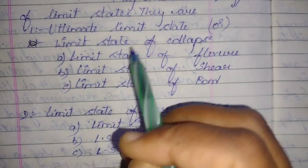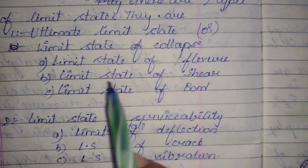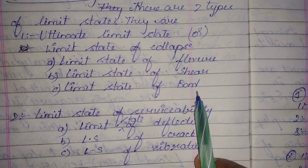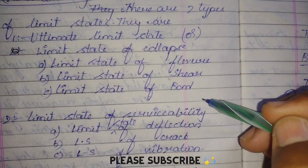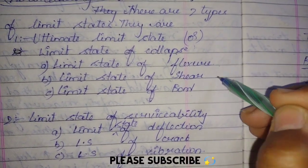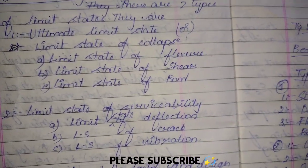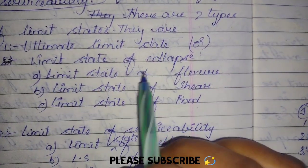Okay, and here it is again classified. The limit state of collapse is classified into limit state of flexure, limit state of shear, and limit state of bond. So whenever we are talking about the ultimate cases, we are talking about this. So generally the flexure or bending is considered, the shear, the bond, that is generally the compression, the torsion, the bending, shear, everything would be coming under this ultimate limit state or limit state of collapse.